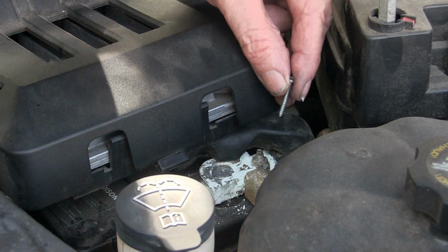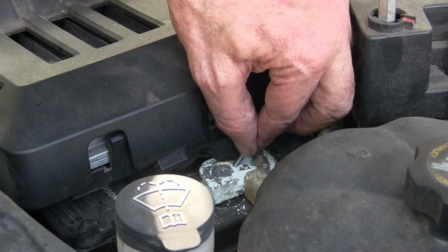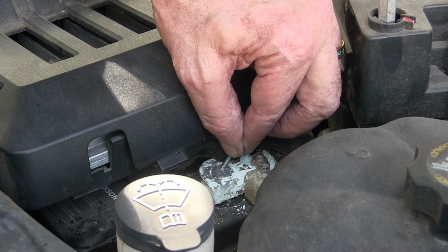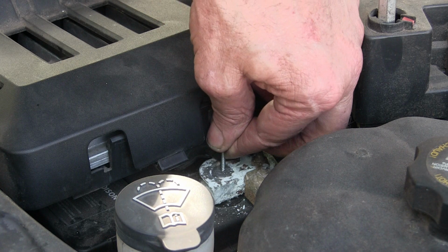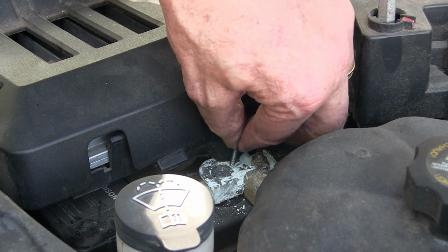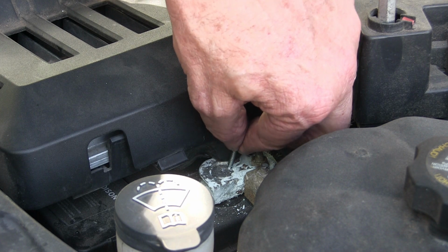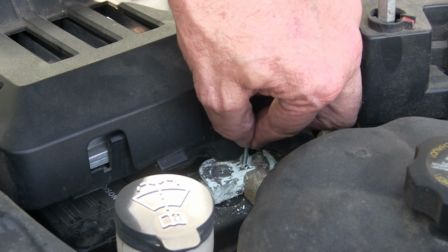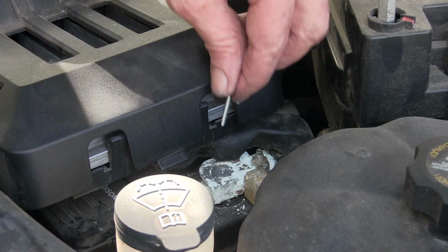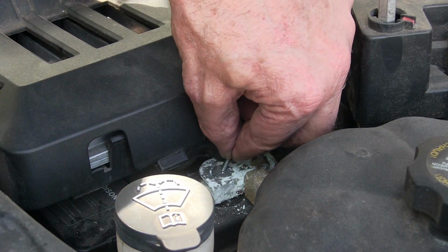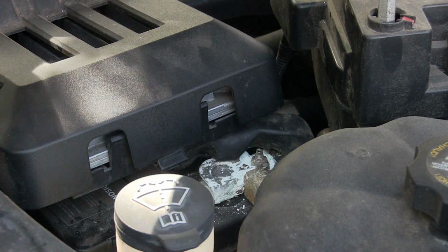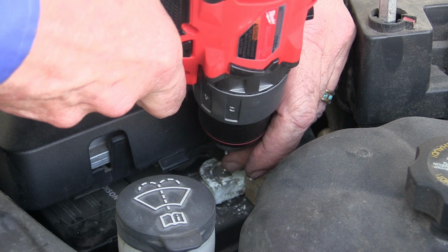Okay, so when you put the screw in, never put it in between the clamp where it could catch the clamp and that post. When this screw goes in, it needs to go directly into the center of the post. If you put it on the edges, it could screw into the post and this clamp, and it can hide your problem, and then you take the screw out and you have the problem back. When we're looking for voltage drops, we always want to be at the battery negative. To make sure we have a good connection, we're going to put this right into the center of this post.